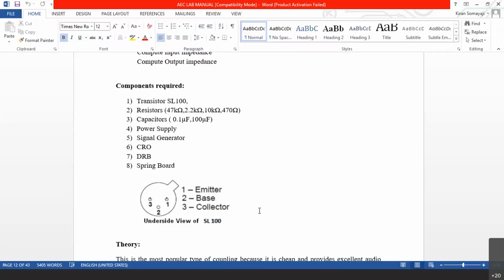Now when you have electrical switches at home, if the switch is on, there is no voltage drop across the switch, because voltage across the switch is zero, so power consumption of the switch is zero. Similarly, when the switch is off, current is zero across the switch. So even though the voltage is there across the switch, there is no current. So power consumption when the switch is off is also zero, ideally.